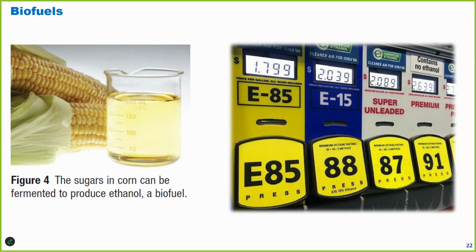A fuel can burn in an internal combustion engine only when it's in the vapor state. Ethanol is not as volatile as gasoline. That is, it does not vaporize as readily and therefore cannot be used directly as a fuel source in most automobile engines. Alternatively, gasohol, a solution of about 10% ethanol in gasoline, will burn in most engines. Another ethanol-based biofuel, E85, is 85% ethanol and 15% gasoline. E85 can only be used in vehicles with specially designed engines.